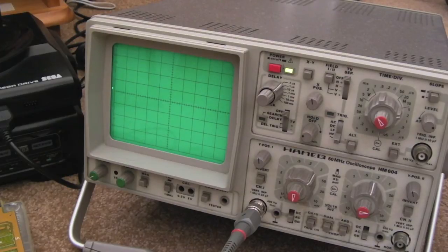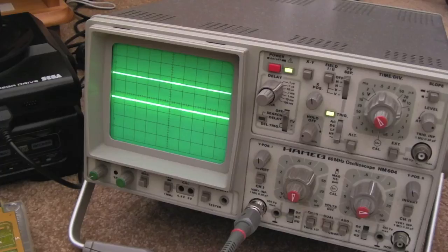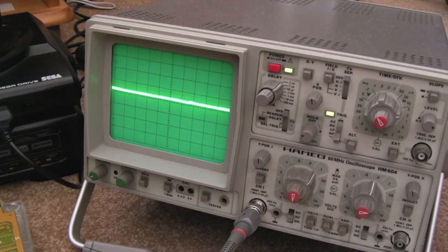Can't do all this on one screen unfortunately, because there's just not enough room in here. I'll show you. Right, so I've got the ground connected now, and I'm going to start with the bottom of the chip. Now straight away you can see that's not looking right. Let's check the next one, and you can see that's what I would expect. That's like TTL level transition between high and low. Oh, and again, that's another data pin. Look at that. That's not right.